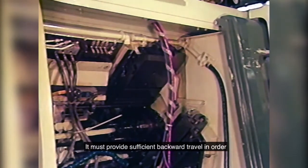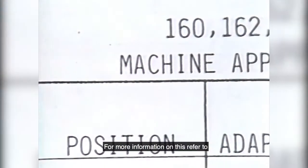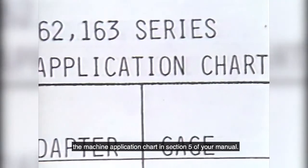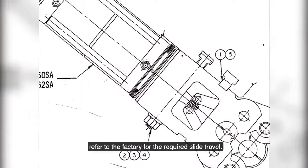It must provide sufficient backward travel in order to clear the attachment during index or other adjacent tooling. For more information on this, refer to the machine application chart in Section 5 of your manual. This chart will indicate whether or not increased cross-slide travel is necessary on your machine, and if so, how much. If your machine is not listed in the chart, refer to the factory for the required slide travel.